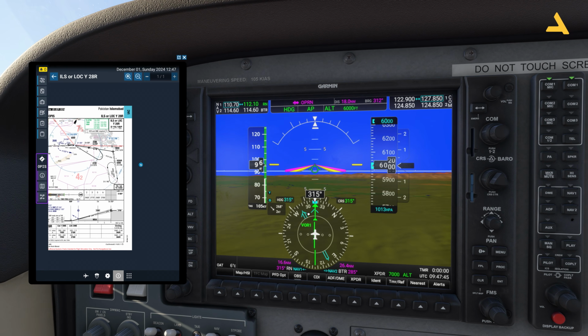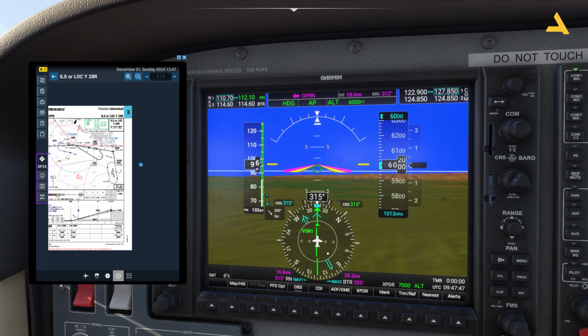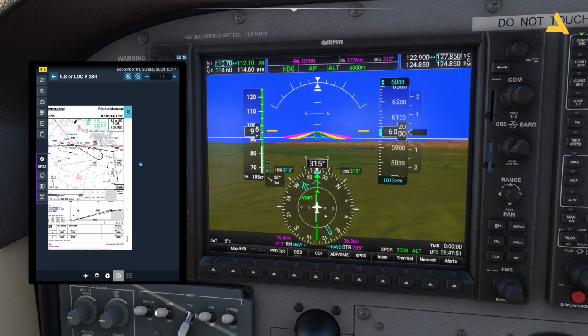If you look at this needle, this is basically your VOR for the Islamabad International Airport. Now this is somewhere here. So this is west, 270, this is 275, and 278 will be somewhere here. So when this needle is here pointing towards this side, it means now you are on this heading. You are going towards this. Right now it's like this, because you're just moving on the radial.